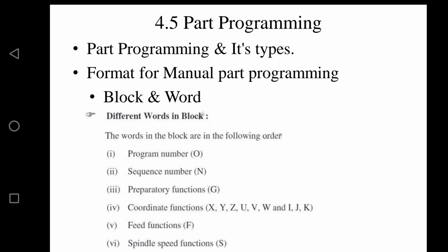O0000 to O7999. Simple or general programs are classified in the numbers from 0 to 7999 following the letter O. And if you are facing custom macro programs, some quite complex programs, then those program numbers will come into the O8000 to